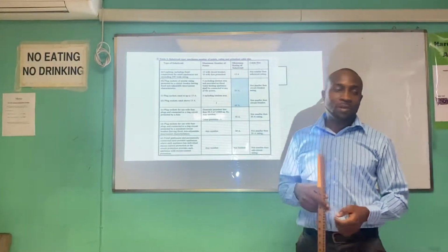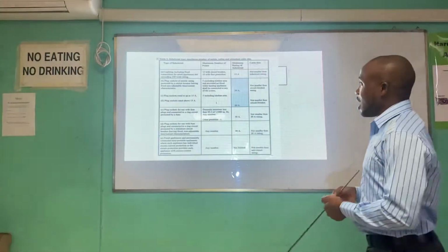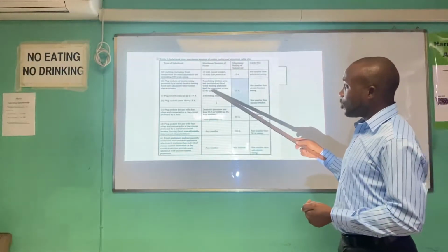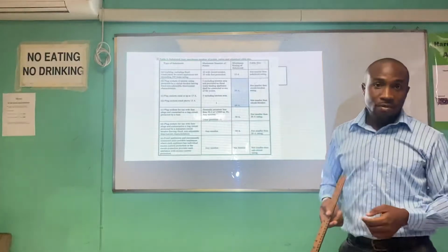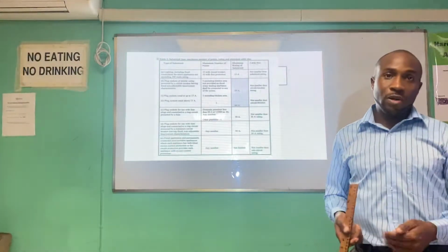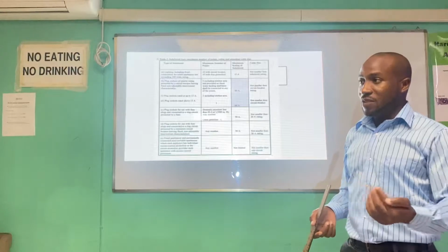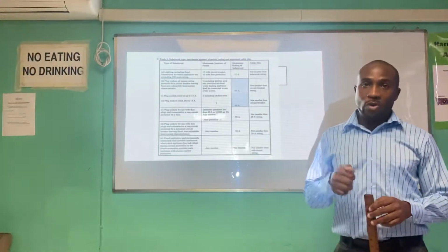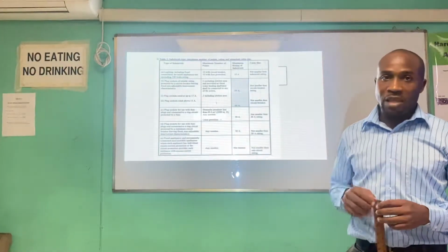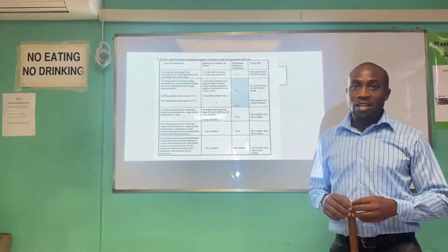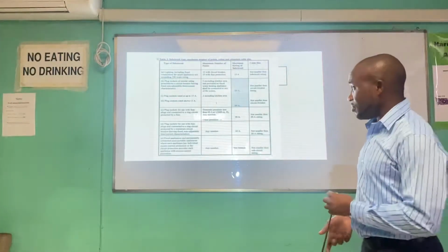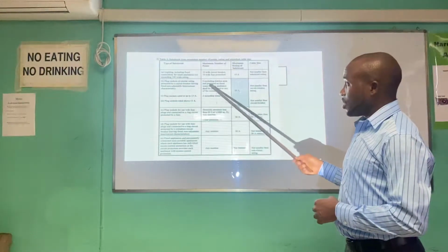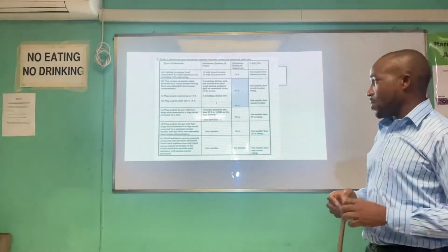And I'll explain that some more because many times we do installations and what tends to happen is that the electrician puts a kitchen plug and a regular plug circuit, where you have your TVs and your fans plugged in, together. What you find is that once you plug your microwave or any of those high energy equipment that you generally use in the kitchen into that socket, the breaker trips. So which is why the kitchen area is excluded.